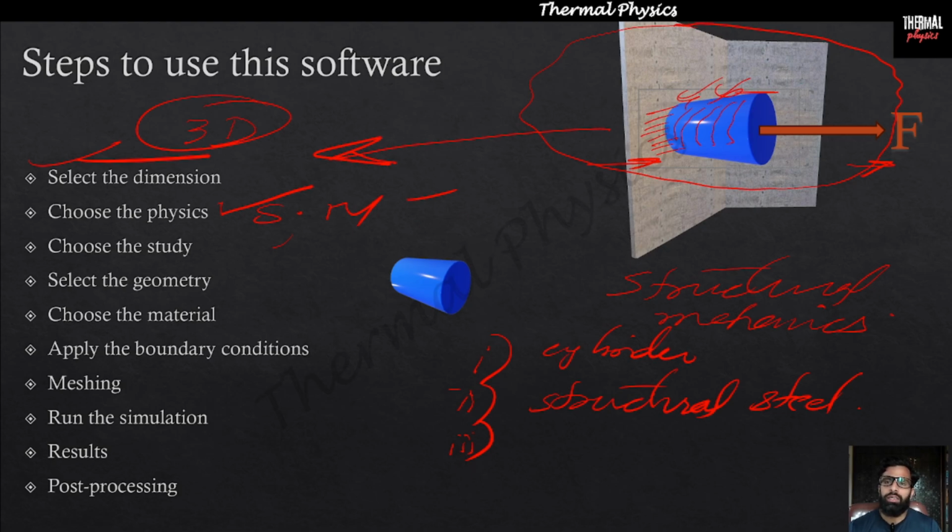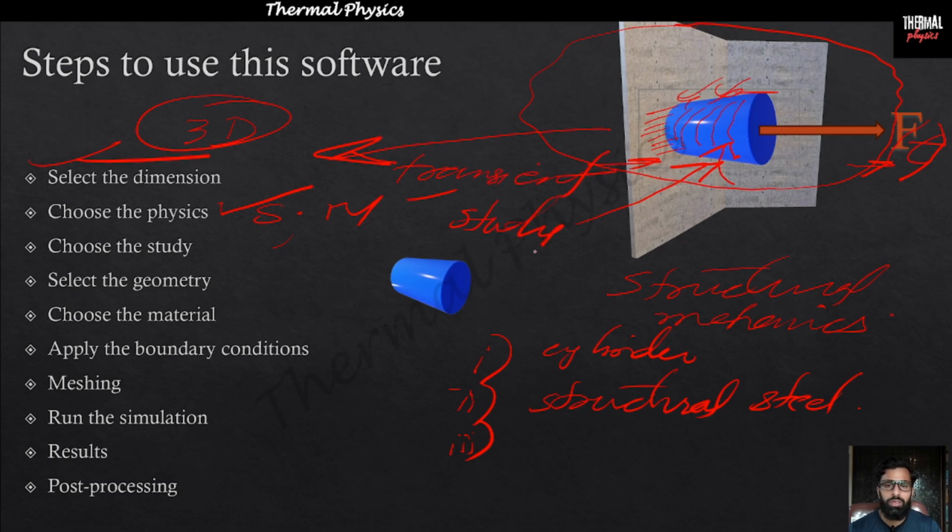One, we want to study the stresses which change with time. Suppose this our force here is changing with time, which means the stress that gets developed, that gets induced in the material, will also change with time, because the loading is changing. When we study such kind of problems which involve change with time, we call it a transient problem, or dynamic problem, transient study.